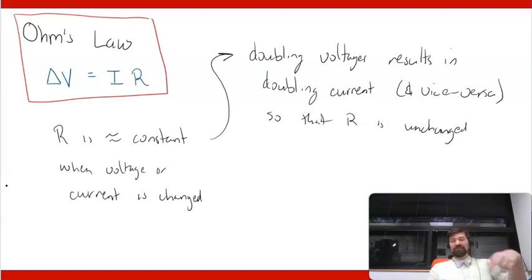It takes some amount of time to elapse for the device to have heated up, and once it reaches a certain temperature, it kind of stabilizes, and then you have a constant resistance, and even if you up the voltage or decrease the voltage, you get very small changes only in the resistance.